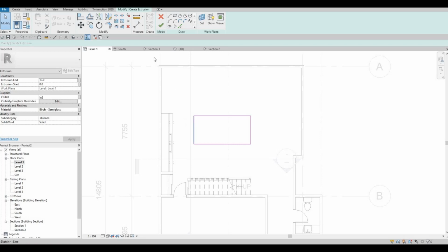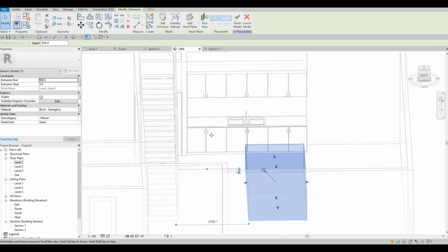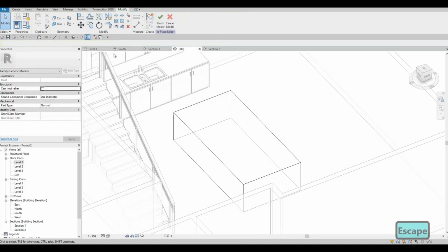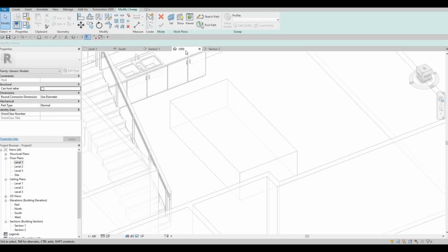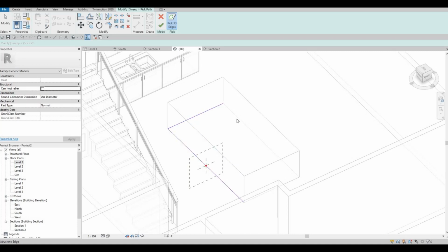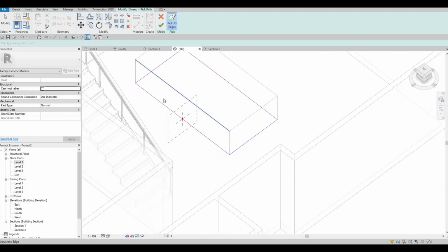And then we have this one set. Let's set it to 900. Click apply. Click finish. But don't click another finish yet. Let's go to 3D. And then let's add a sweep void, which I'm gonna do here. And then let's pick the path. We're gonna pick this path. So the below one, we're gonna create the kick plate similar to what we did there.